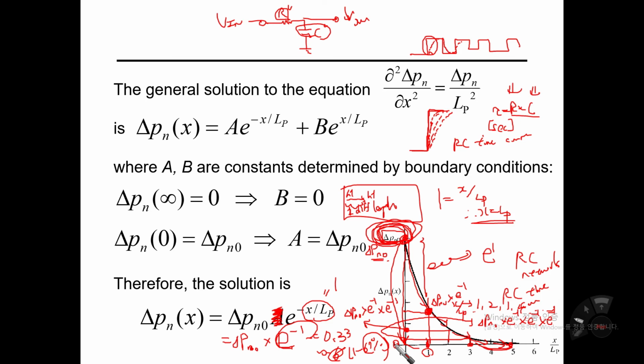Okay, this is a really important idea. In device physics, such as a PN junction diode or MOSFET, for a given externally applied bias, the way excess carriers decrease follows the exponential. The total number of excess electrons or holes is decreasing exponentially.